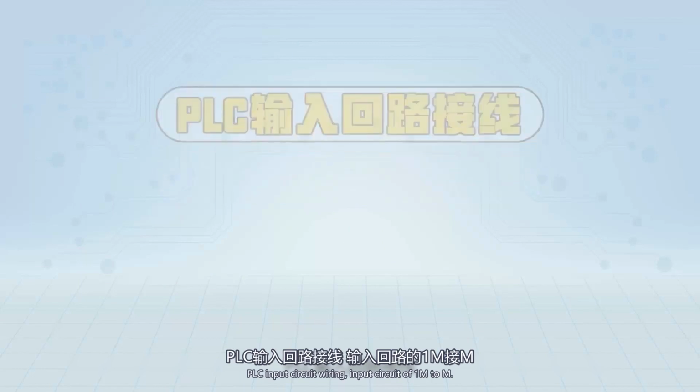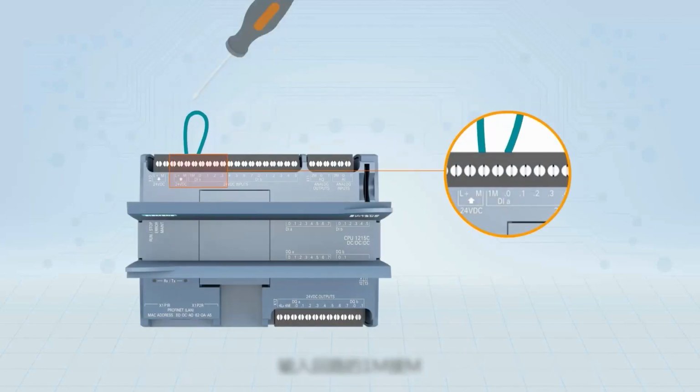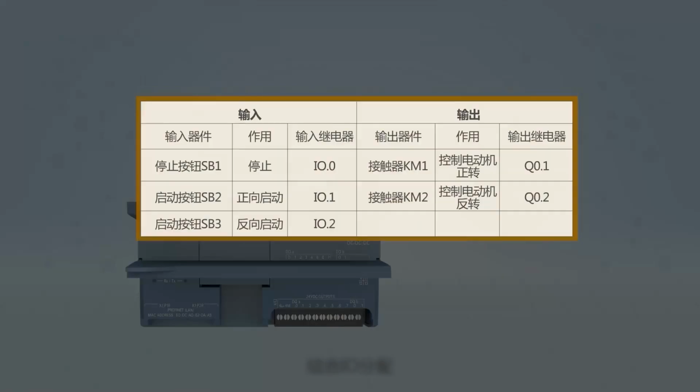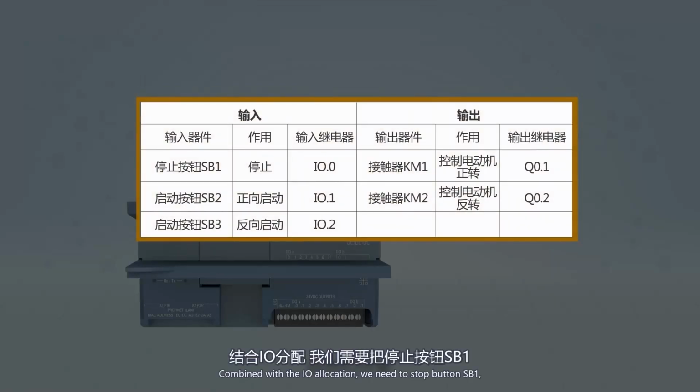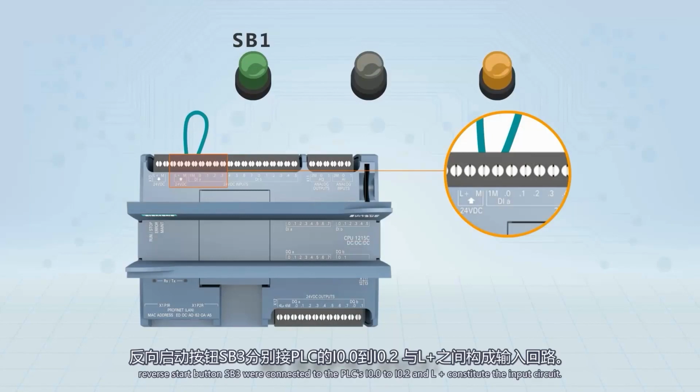PLC input circuit wiring, input circuit of 1M to M. Combined with the I/O allocation, the stop button SB1, forward start button SB2, and reverse start button SB3 are connected to the PLC's I0.0 to I0.2 and L+ to constitute the input circuit.